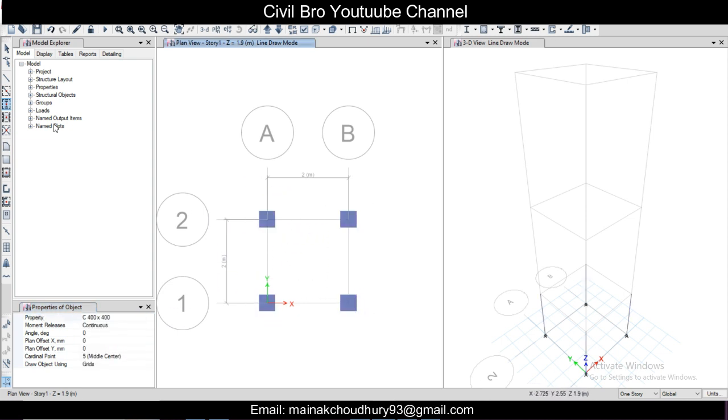So the columns are prepared, and then we have these quick draw beams. We'll take the property here, and take the property P300 by 500.